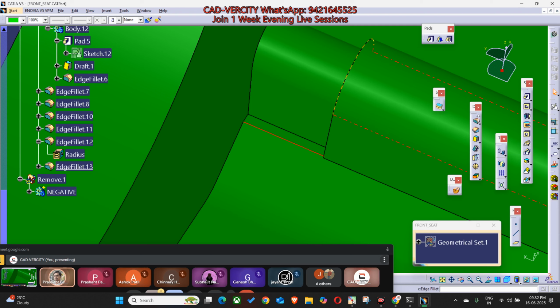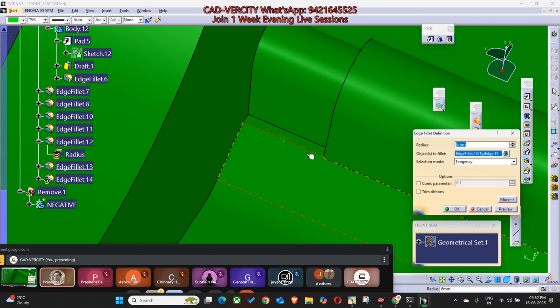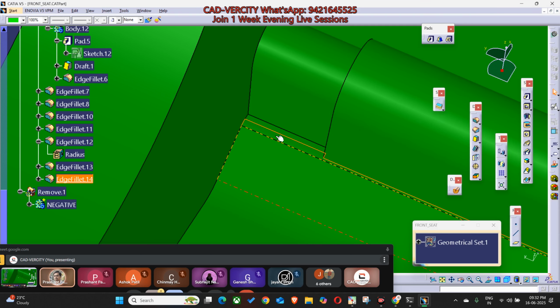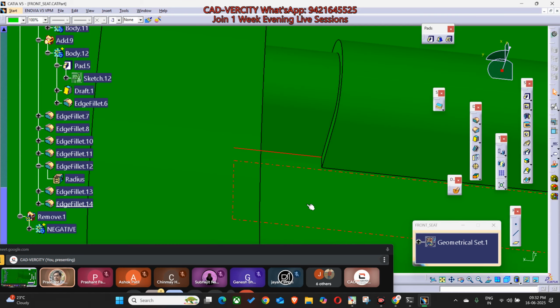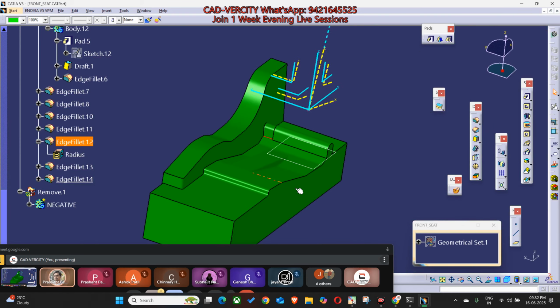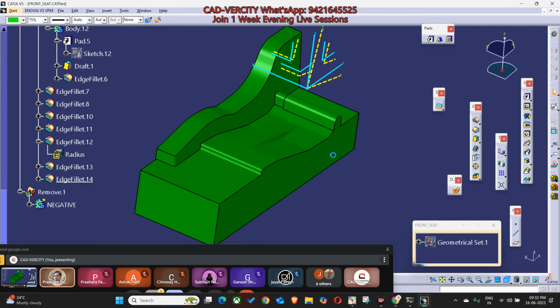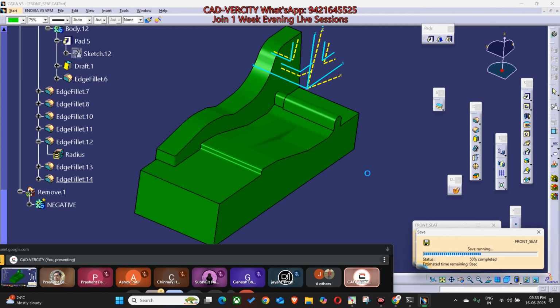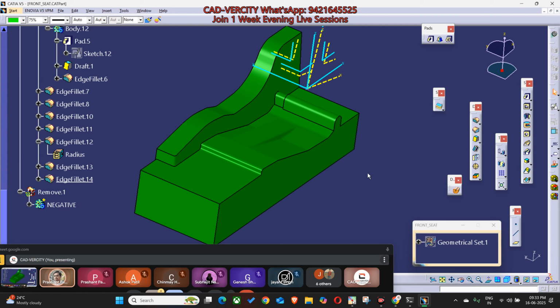So apply. Hello, sir. There is no doubt, sir. Yes, Prashant. Sir, in the B tool, if we are applying the fillet a minimum 5, right, sir? 5 or 6. Yes. If there is an edge which is not taking a 5 radius, then what will be the option for that? Yeah, in that case, you can apply, but try to keep more than 5, 6 mm.